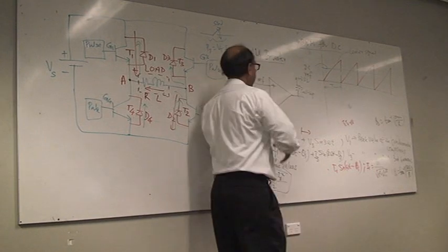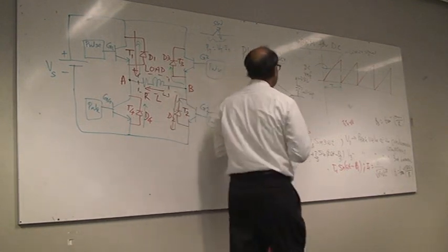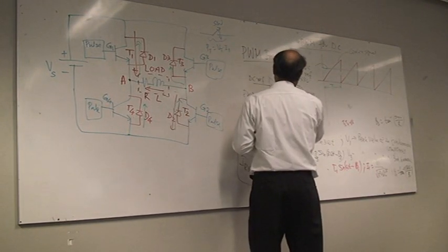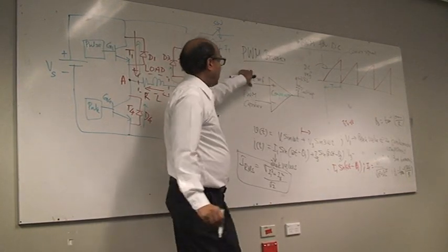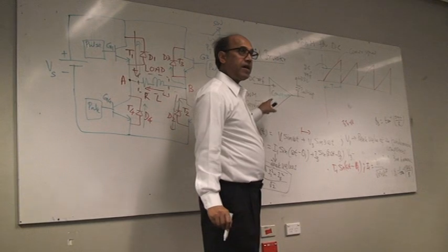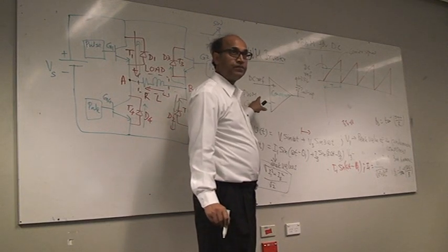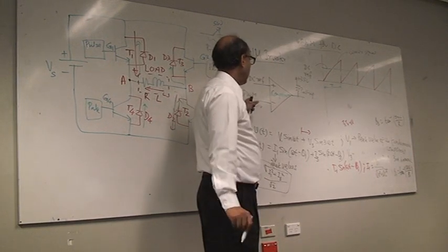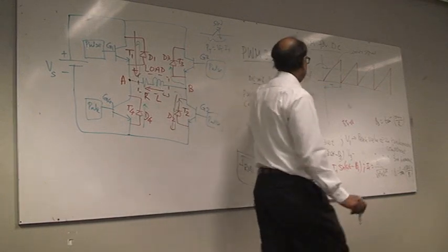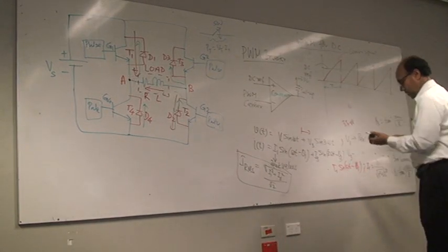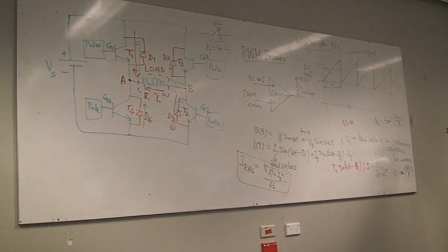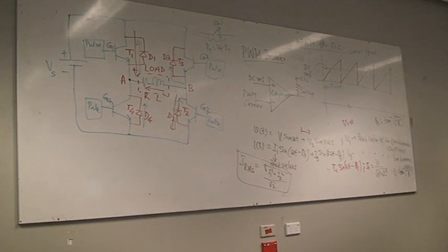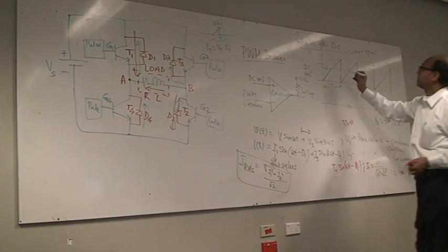What does this comparator circuit give you? When your plus is higher, you get high. When the plus is lower, you get 0. So you think of a unipolar supply. If I now plot my voltage, what do you expect I get here?